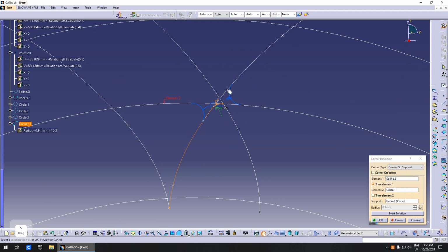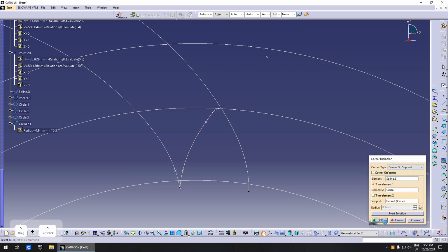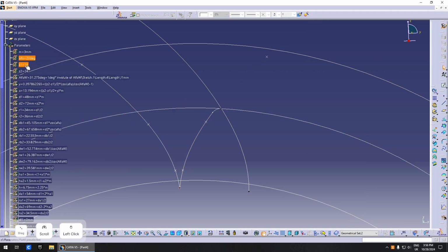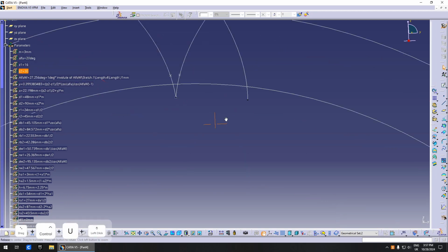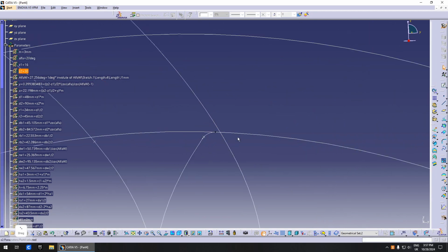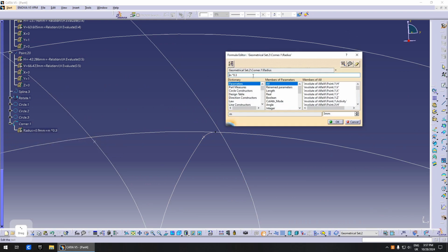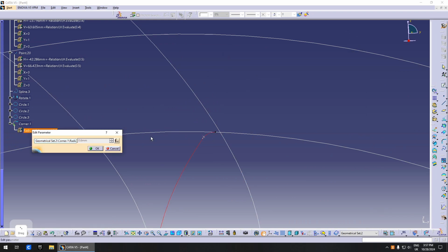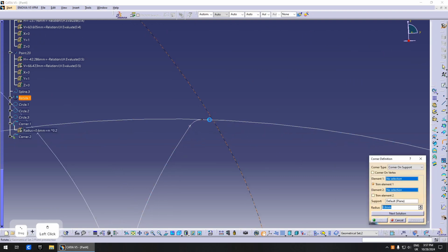One, you can actually undercut this and make a bigger cutout here. 2, you can change the profile shift of the gear. That'll help you solve it. And 3, you can change the number of teeth. So this difference here is probably not that great. So you can have something like this. You can also reduce the radii here. So this is like 0.2 times the module or something like that. That should be enough.